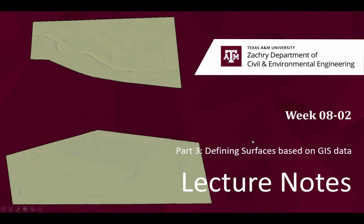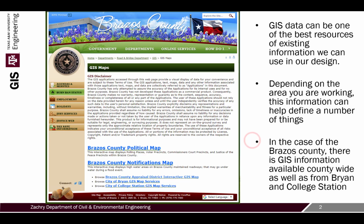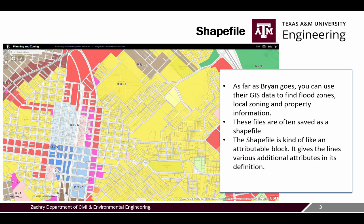So this is week 8-2, and in it we're going to be defining a surface based on something different from point data. In this case, it's going to be GIS data. You can pull GIS data from multiple sources. A lot of the information I've had has come out of Bryan or Brazos County. If you click on it, there are certain shape files that you can use. And like we said, a shape file is like a block with an attribute.